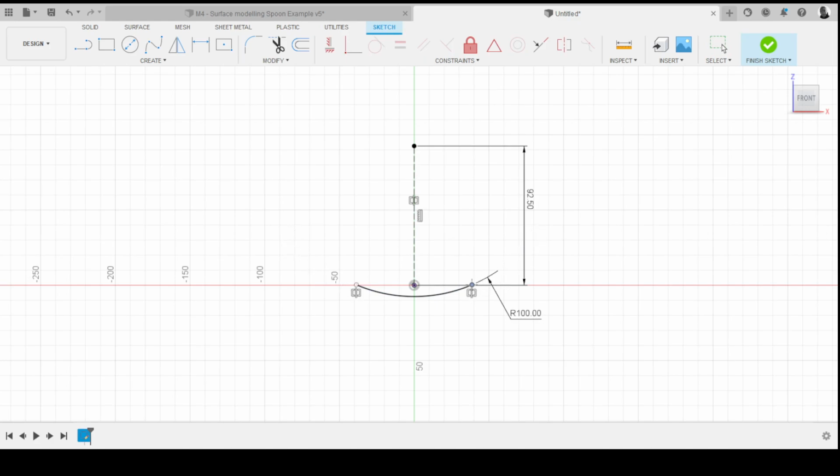Now if I move it in and out, it will retain that symmetrical constraint. So symmetry constraints are really handy. I just thought I'd show you that, because it's a handy thing. If you had selected the points the other way round, would it have shortened the longer part to match rather than lengthened the shorter part? Good question. Probably. It would seem logical, wouldn't it? Yeah, there is a logical order: the first selection is where you want it to go to, and then it moves the other one to it.